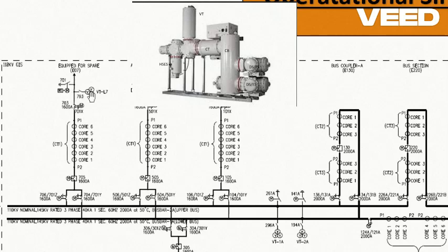Then VT, voltage transformer. The purpose of VT is to measure the high voltages, because 132 or 110 kV voltage cannot be measured directly through voltmeters. Voltmeters only measure low voltages like 110 to 120 volts. But here it is 132 kV. There is no meter to measure this voltage. So to scale it down in a proportionate way, these VTs are designed.